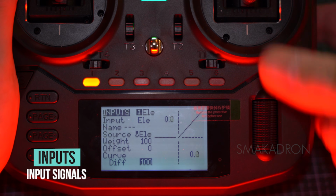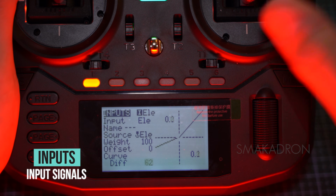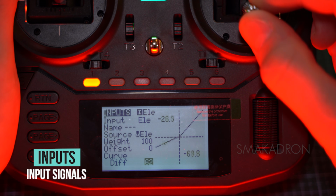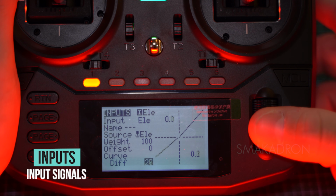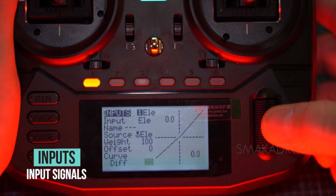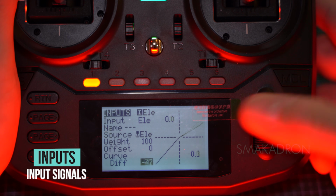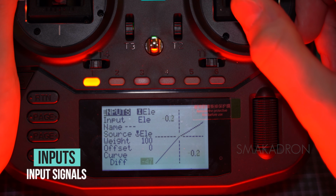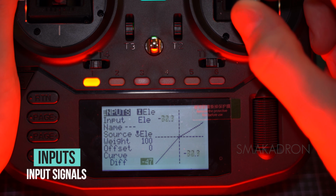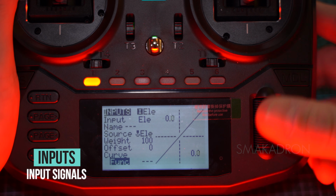Diff multiplies only the range above or below the center zero by the specified percent. Suppose you want the model to be more sensitive to stick movements in the positive range and less sensitive in the negative range. You can configure diff to multiply the positive range by a larger percentage and the negative range by a smaller one. It allows you to adjust the stick's sensitivity separately for different ranges of motion, ensuring precise control over the model.